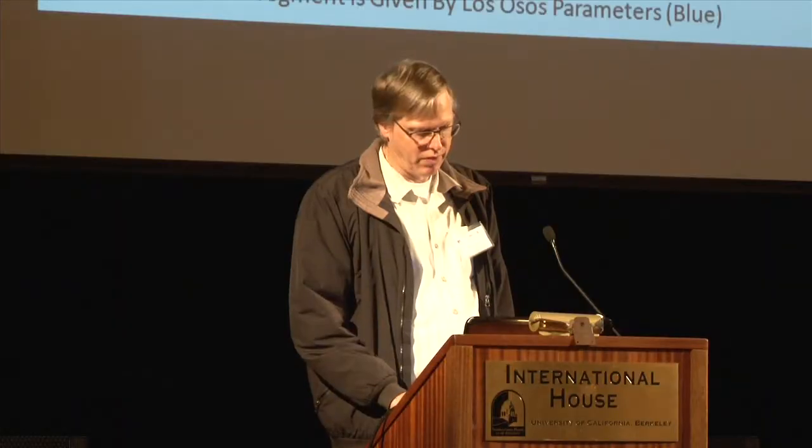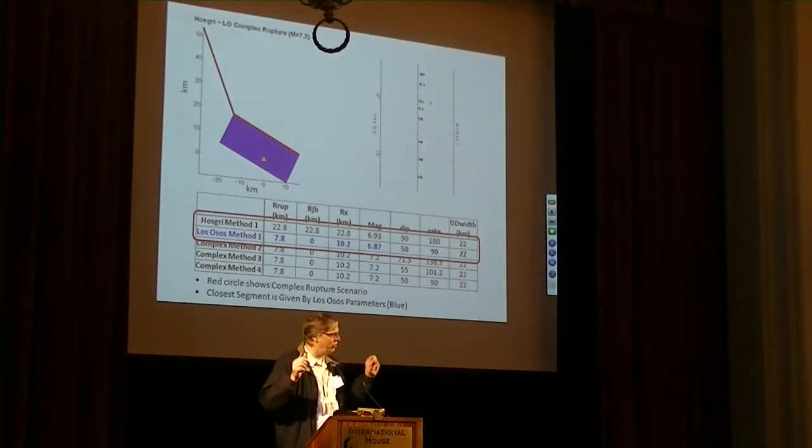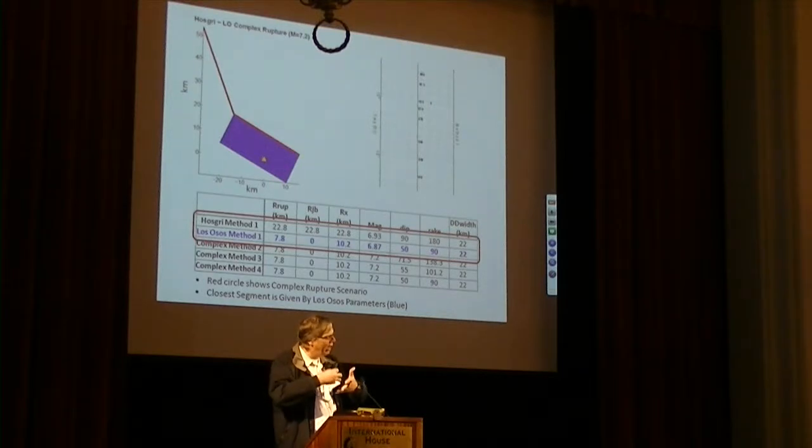SRSS is independent of the distance of the station to fault? If you SRSS them, so if this was my case here, I would take the distance from the station to this part, treat it as a separate earthquake. Then I get the distance from my site to the strike slip part. Okay? So it's like the two separate earthquakes. We're going to compute the ground motion from each of them, and we're assuming that they interfere in time so that the strong shaking is overlapping from those two parts of the rupture. Okay, and so then we can use RVT and SRSSing it.